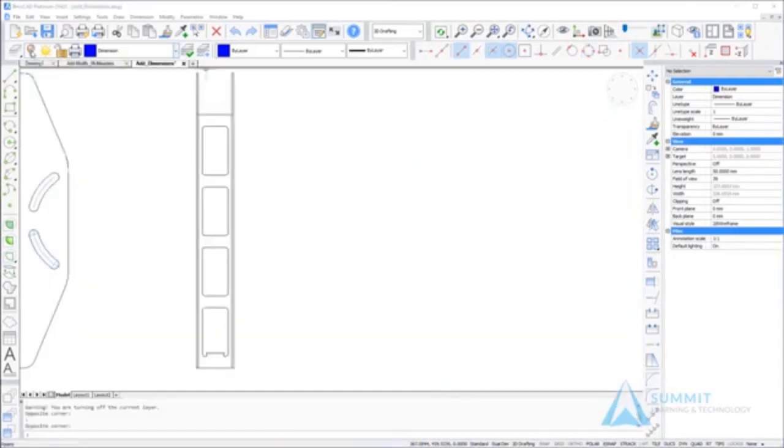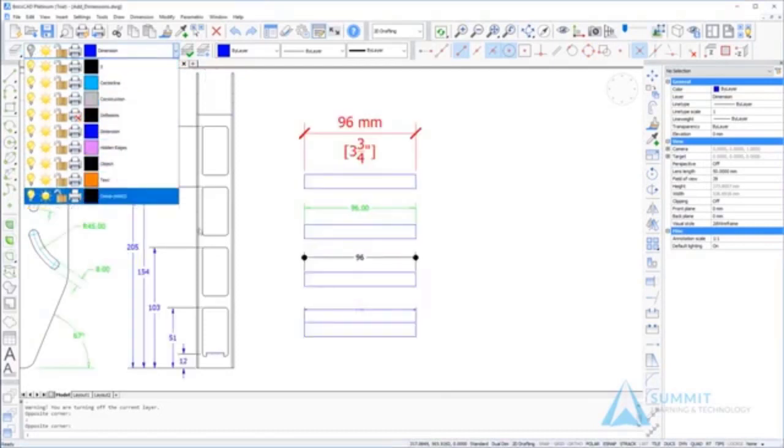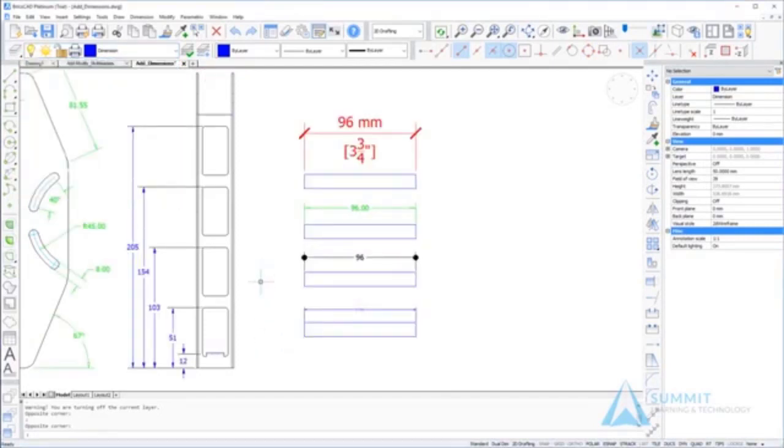The end result, as you will see as you progress through this lesson, is you're going to create several dimensions on this drawing, and those dimensions will be associated with the dimension styles. If we look in this area of the drawing here, we have some examples of using dimension styles. So we have the same identical shape repeated 4 times, but dimensioned using dimensions, which have been assigned different dimension styles, and or the properties of the dimensions have been modified manually using the properties palette. So this is a great example of how you can use dimension styles to control the appearance of dimensions in your drawing.